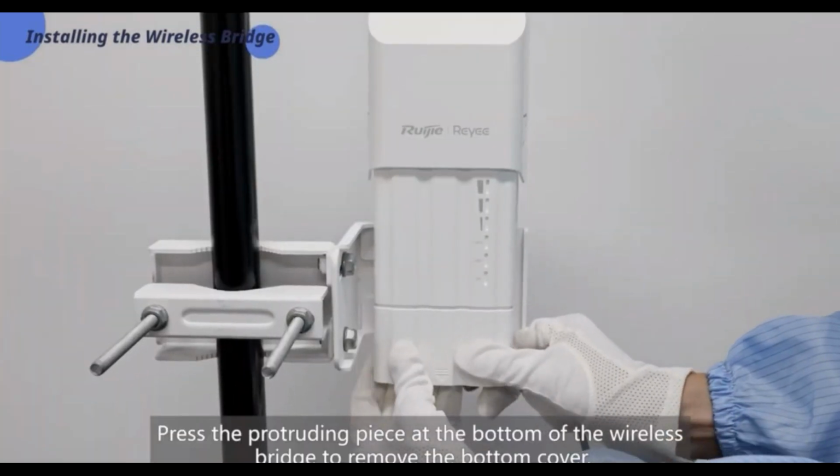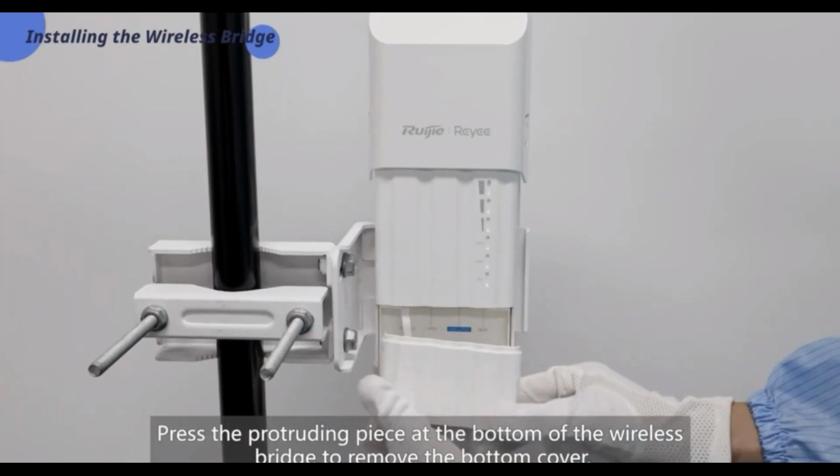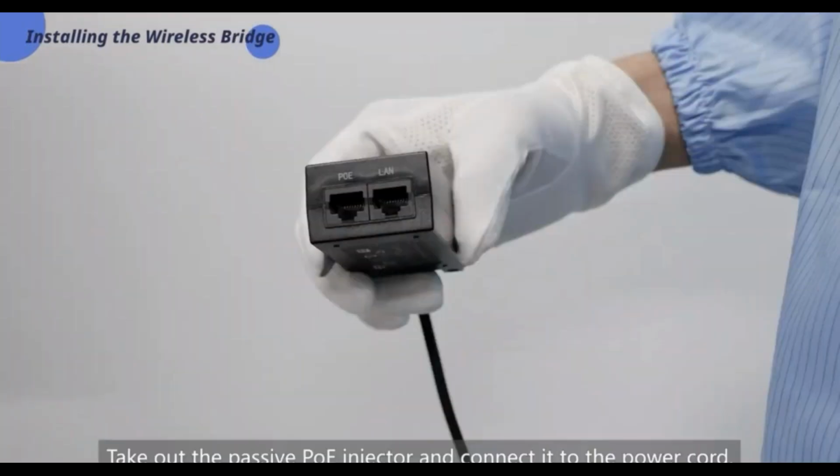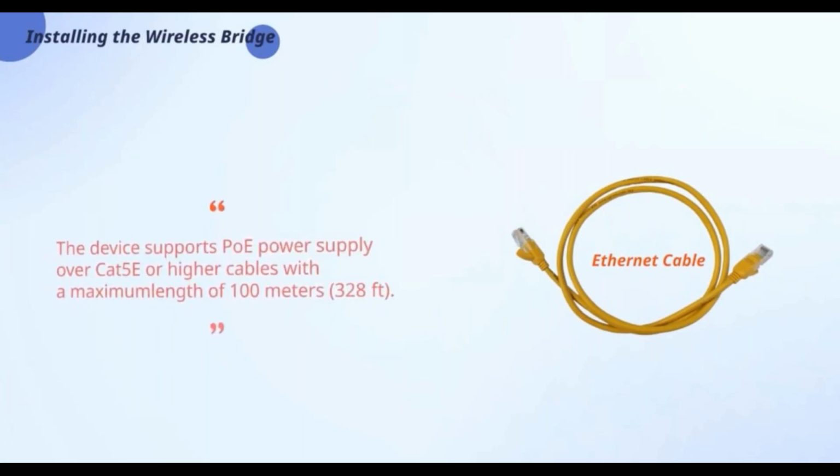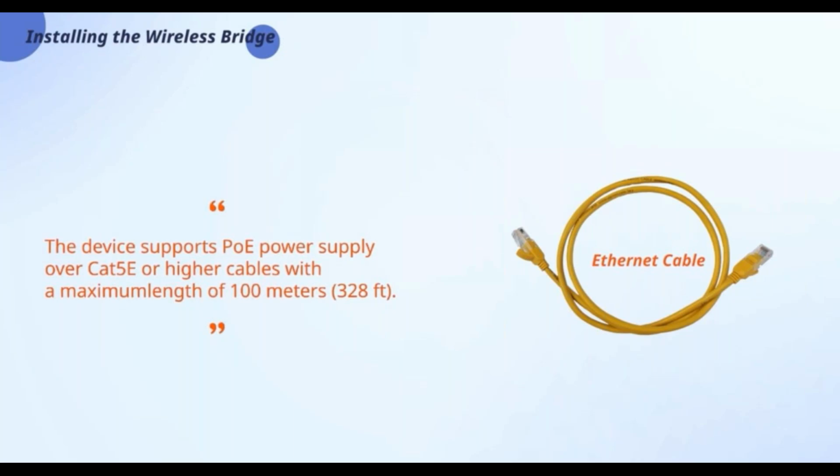Press the protruding piece at the bottom of the wireless bridge to remove the bottom cover. Take out the passive PoE injector and connect it to the power cord. Use or make an Ethernet cable based on the distance between the wireless bridge and the power source. The device supports PoE power supply over Cat5e or higher cables with a maximum length of 100 meters, 328 feet.